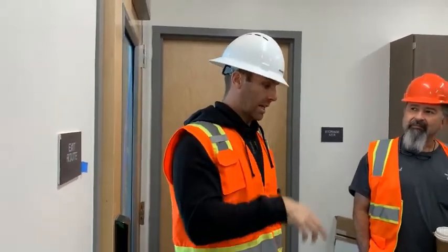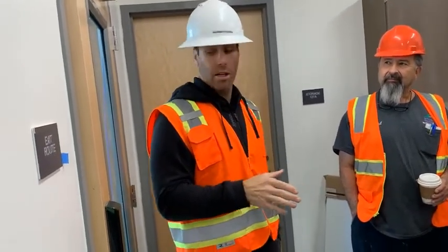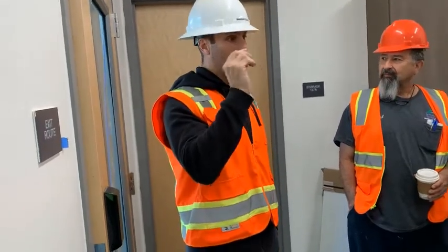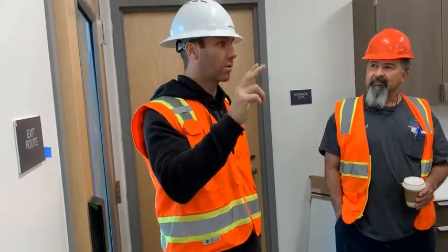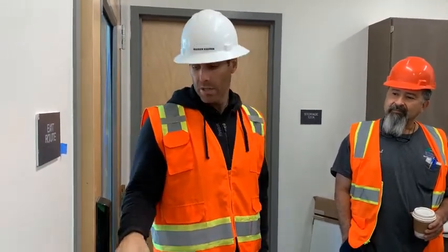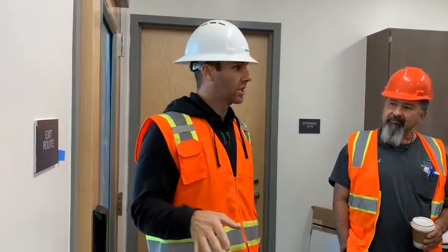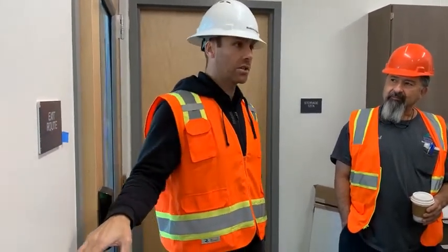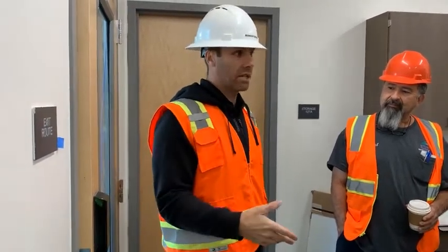If we look at this as a single room, it would not have to be connected to the system. It would not have to be connected to a bridge, the eclipse, anything like that. These fixtures put power over the Cat 5, that 24 volts, those 2 wires we're talking about on the Cat 5, and that powers this switch, okay? As long as I have this little green LED, I can turn the lights on and off, everything's good to go. This aux sensor is going to be set at 10 minutes, the dim at 7.5.